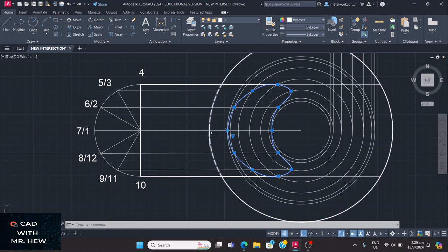This is the base of the cone. Below the cone, this is the base of the cone in the plan, and the cylinder is above it. So this will be in hidden detail. Likewise, this part here is below the cone, so this will be in hidden detail.